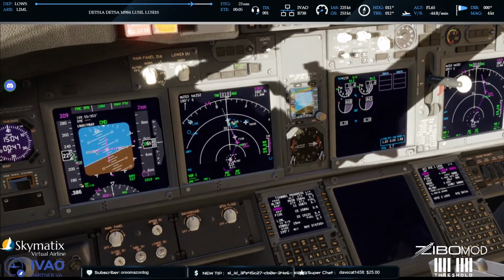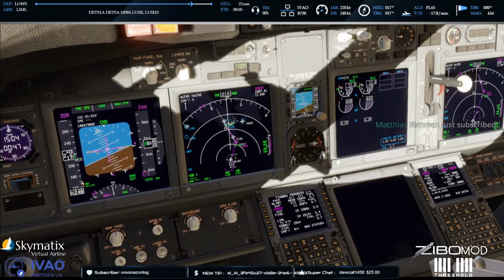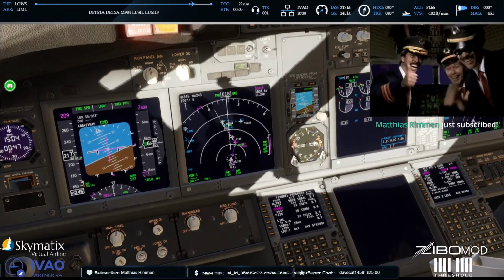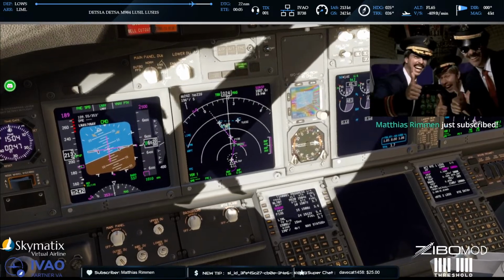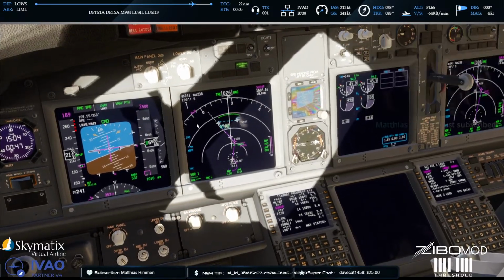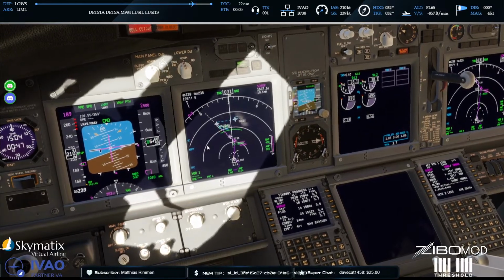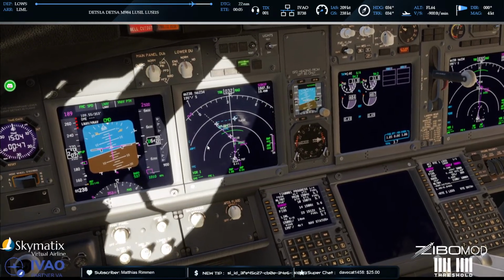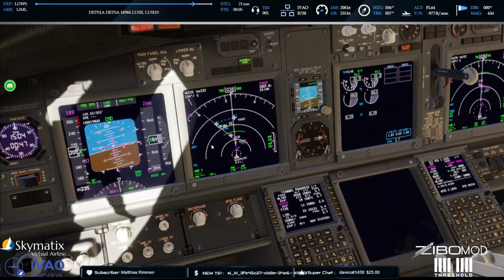Yes, exactly. Ice idle is a kind of middle, but it's approach idle, technically. My understanding is it's an FAA requirement for the approach idle to guarantee a maximum of 8 seconds, yeah, to have go-around thrust. Flaps 1 set. That's it.